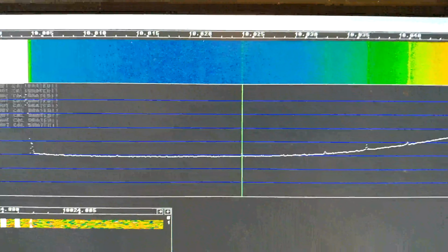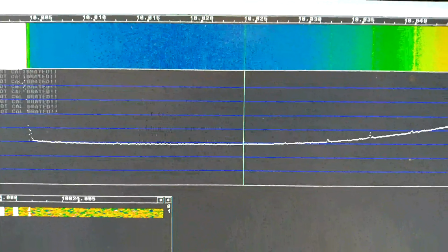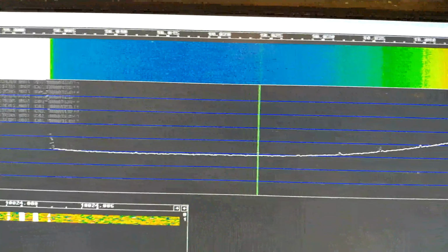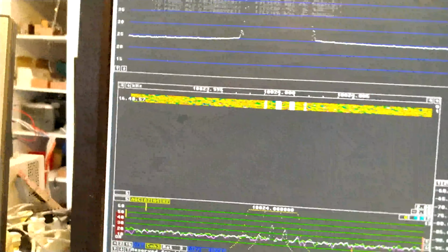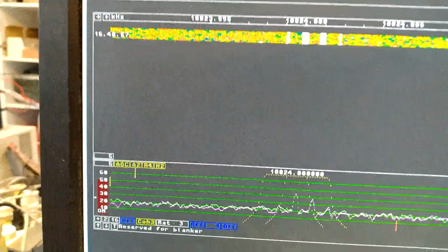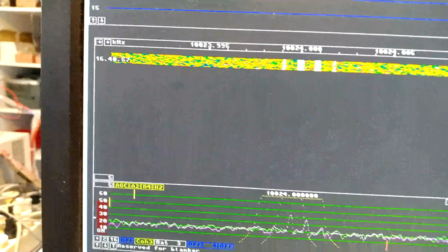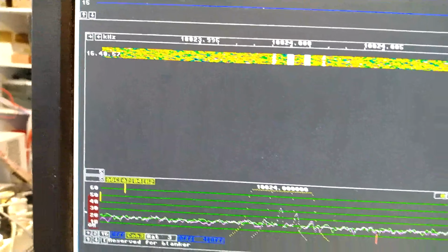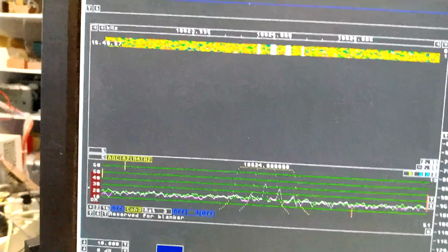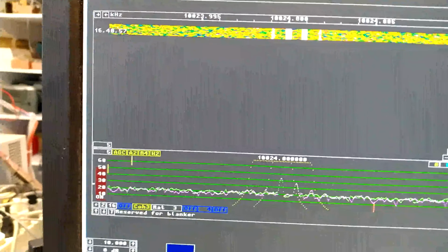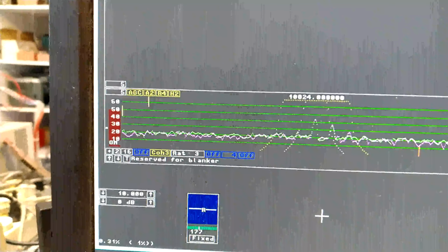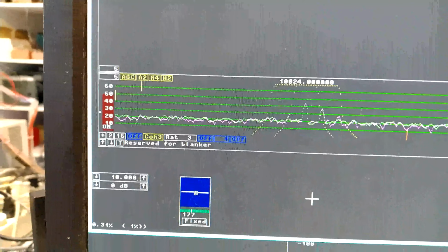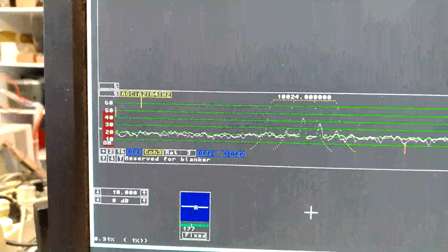I can look at the spurs in normal processing mode without correlation. The strongest one is at 24 kilohertz. So I look at it with high resolution in the baseband, and then I can see there are actually 4 signals there, which explains why it looks so ugly when I look at the sideband noise. It is the same in both channels, which you can see here.